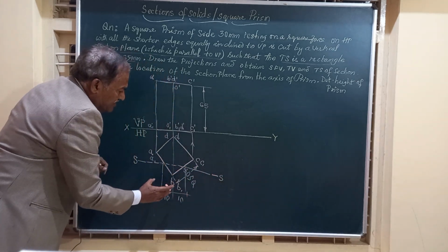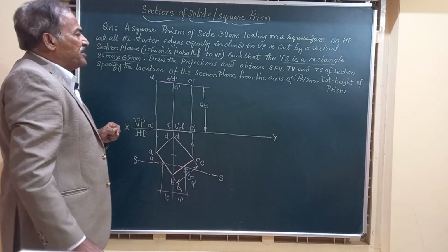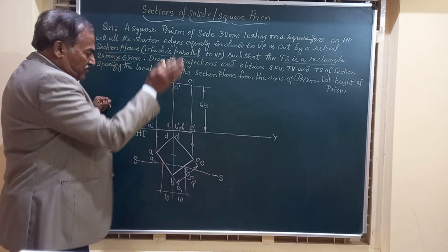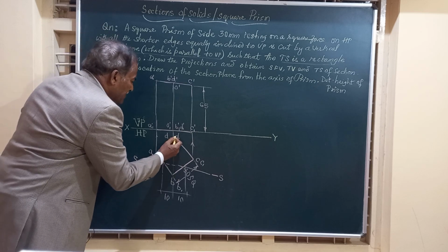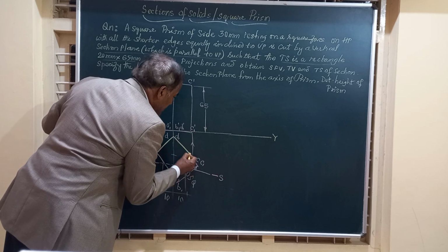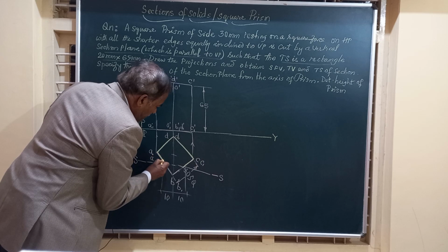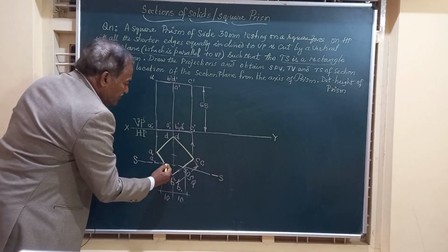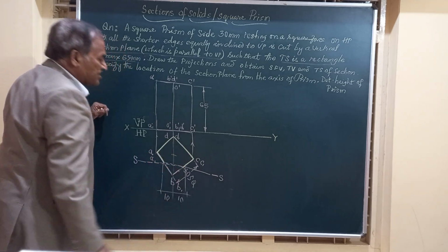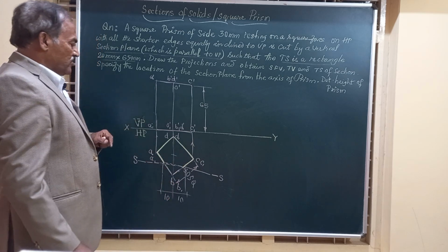It is passing at some distance from there, which you are going to find out later on. So friends, after obtaining a vertical section plane which is parallel to VP, let us write down the portion of the solid that is left over after throwing away the part near to this. Here this much portion of the solid is retained, this portion is removed. Section below section plane, this is removed, and these are the points you have got.